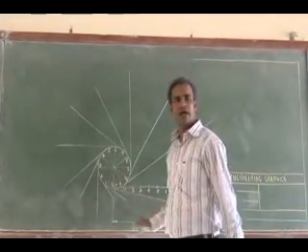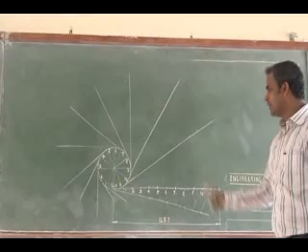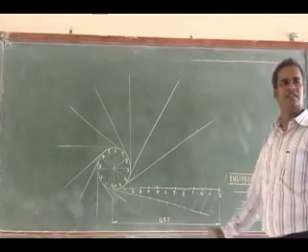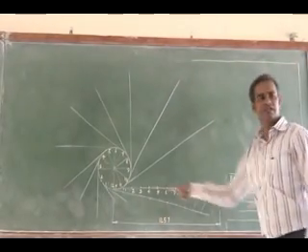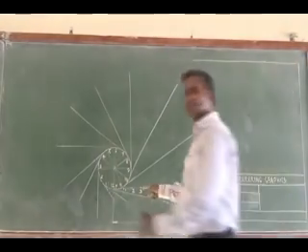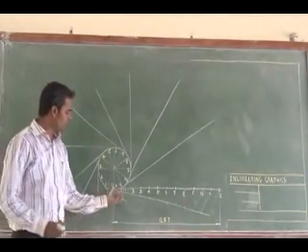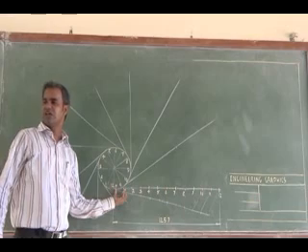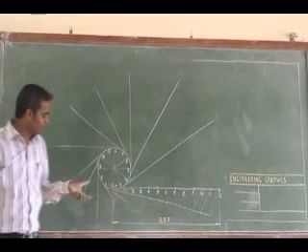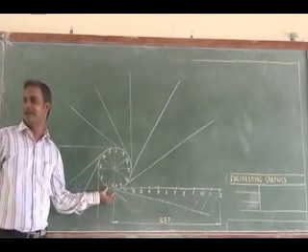How can I do it? I can mark 12 points on these 12 tangent lines. Already you have 12 segments here. The first segment length from point P, you can measure in your compass, and transfer it from point 1 to that tangent line.